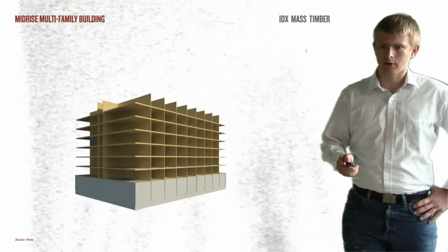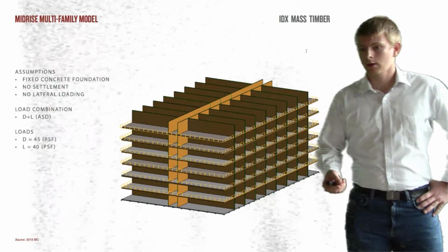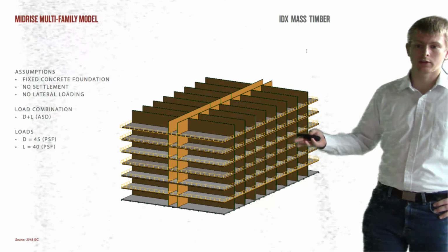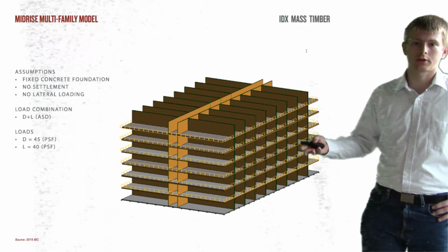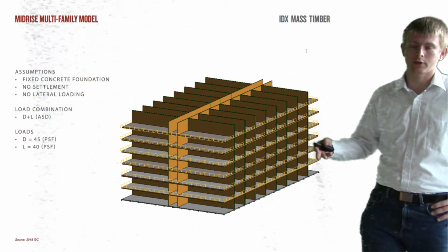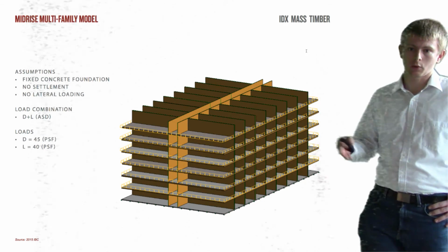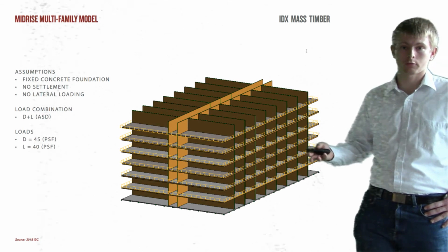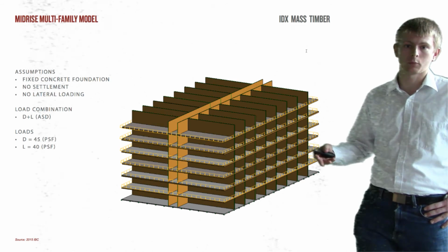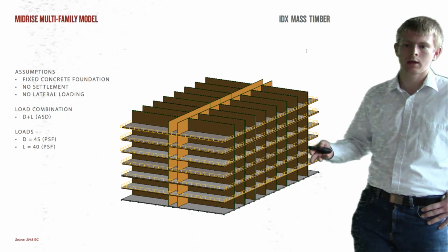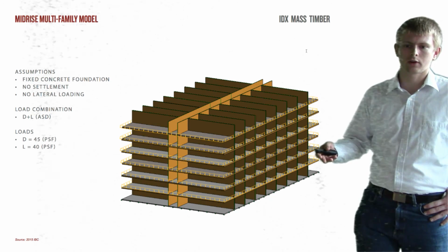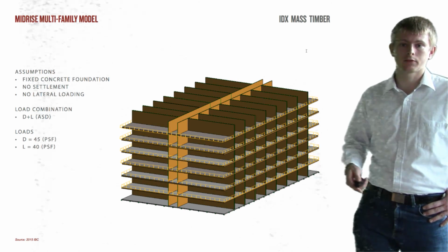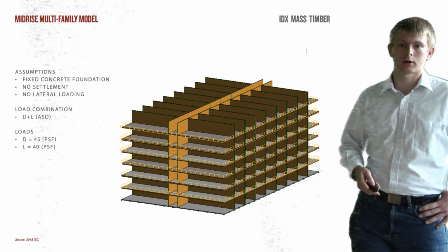So what I did, in Revit as well, is add loads to each level, dead plus live. Some assumptions that went into this model are that it is a fixed concrete foundation, so the podium that you saw on the previous slide was replaced because we did not want to add that to the analysis. No settlement and no lateral loading at this point. This is a preliminary analysis. We'll delve more into that at a later time. But the dead load for this model was estimated at 45 PSF, and the live load was 40 PSF for residential.